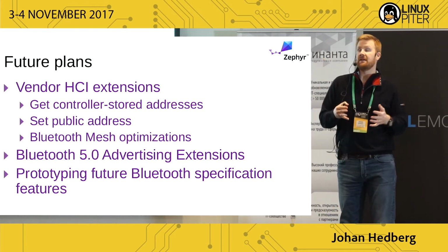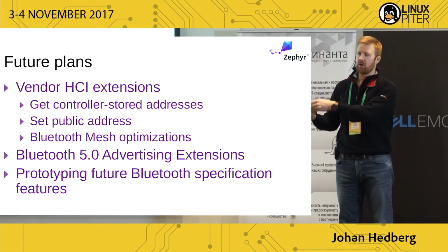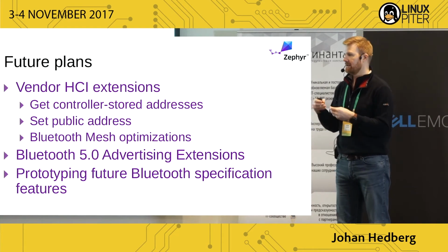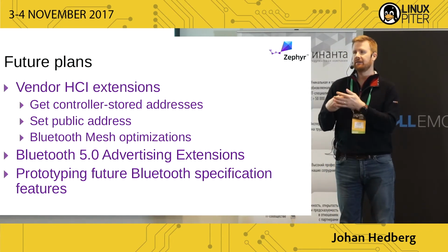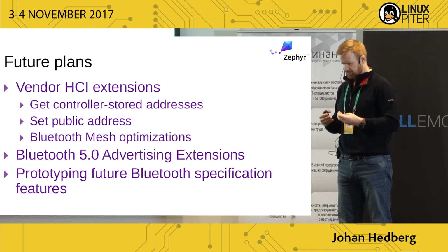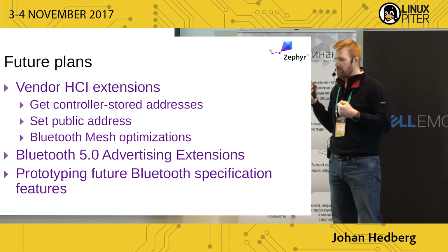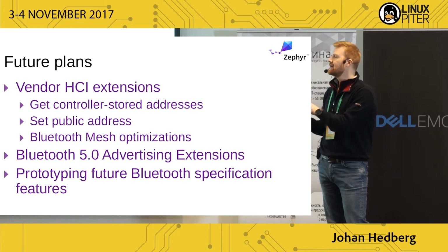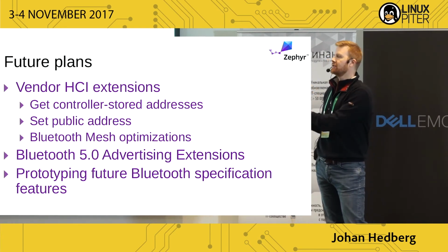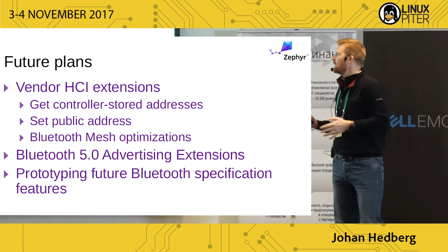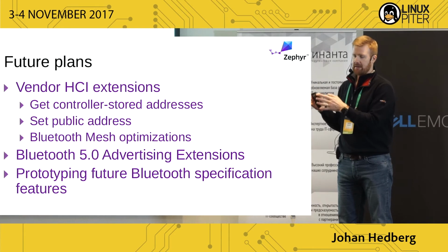Since we have our own controller implementation now that's fully open source, we can do many things which we have never been able to do before with controllers with a closed source implementation, where we can't tweak the internals of the controller. And one of the pain points with the standard HCI is that if you have a solution where the host sits somewhere different, and you don't want to have the controller pre-programmed with a fixed public address, there's no way to do that with standard HCI. So we actually already have defined an extension to HCI where you can tell the controller to use this public address.